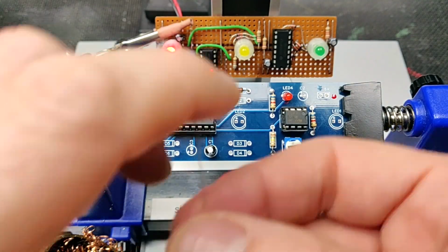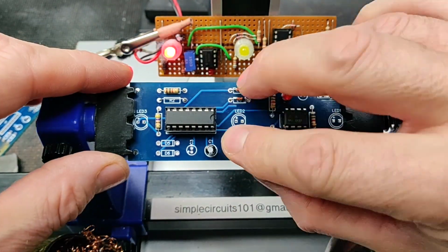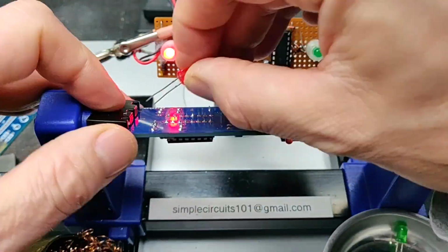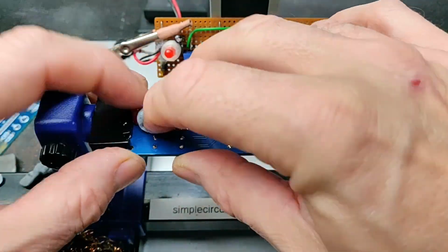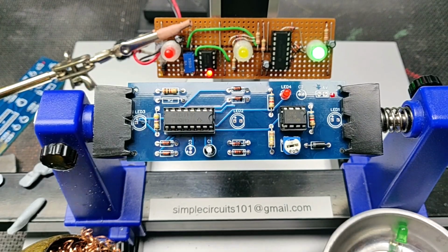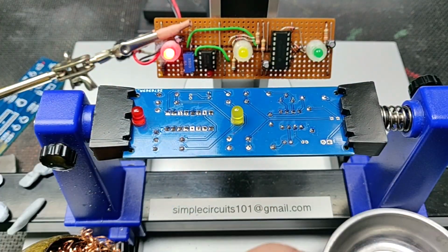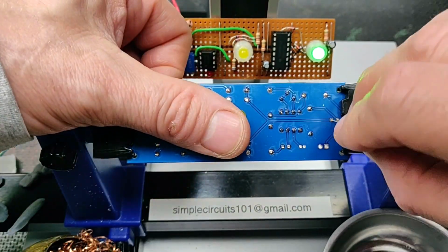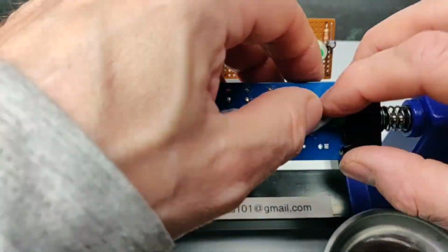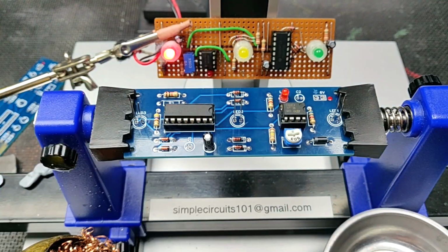And put the diodes in, make sure they're the correct polarity, and do the bottom diodes as well. Just true them in position. Another LED, just checking the polarity, but placing it on the underside of the PCB. And solder in place. Yes, this doesn't flow. Rotate, remove the blue tack and pop in the other LED, the amber one this time. Same deal with the green LED. Secure them all with blue tack and solder just the one leg and true them in place.